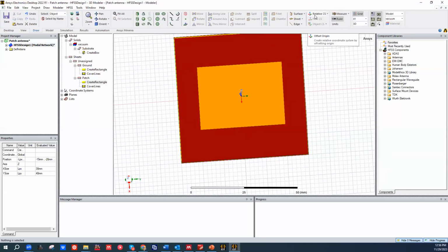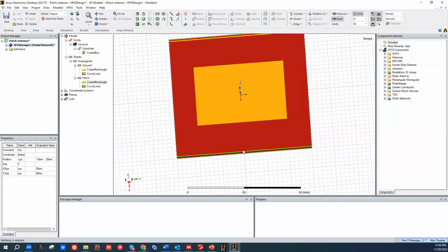It's useful now to change the reference coordinate system and create a new, local one somewhere, I mean, at this point. So we will count all the size and position of the microstrip according to this point.